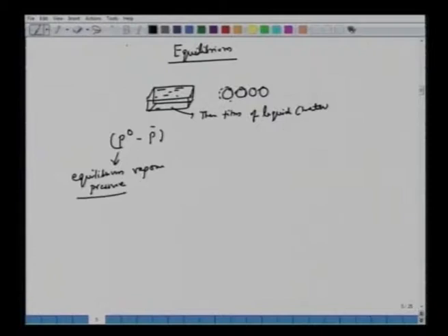Alright, equilibrium vapor pressure. It's the moisture here, and make a note that this equilibrium vapor pressure need not be the vapor pressure of pure water. That's another difference we have here. If pure water has a vapor pressure, say P0 at T, it's possible that the vapor pressure at the solid surface need not be P0 of water at T. We'll see that there are two different ranges.